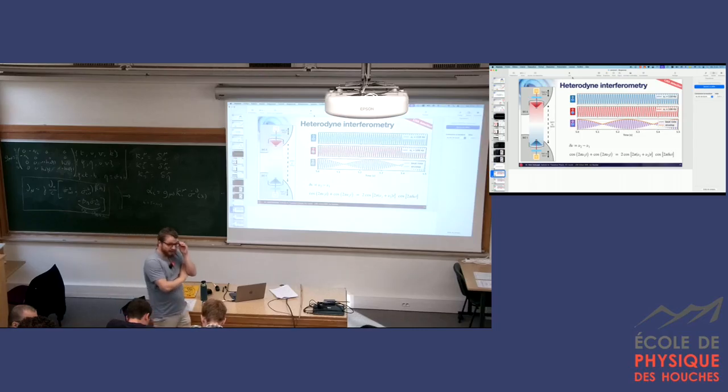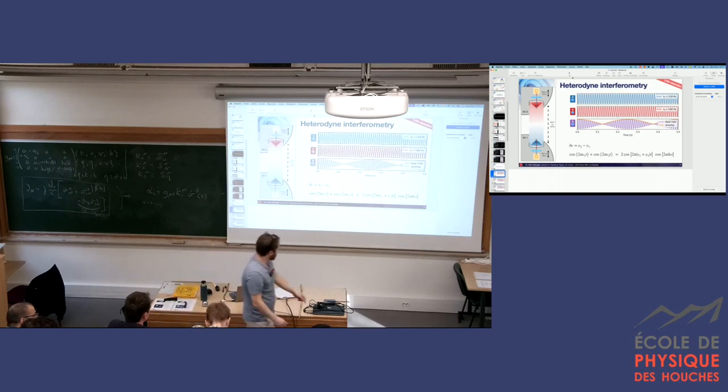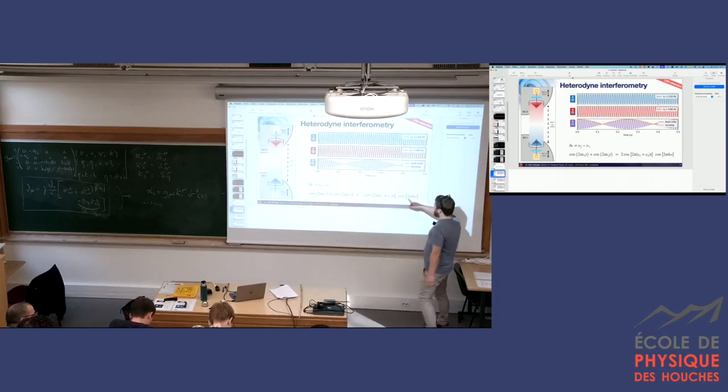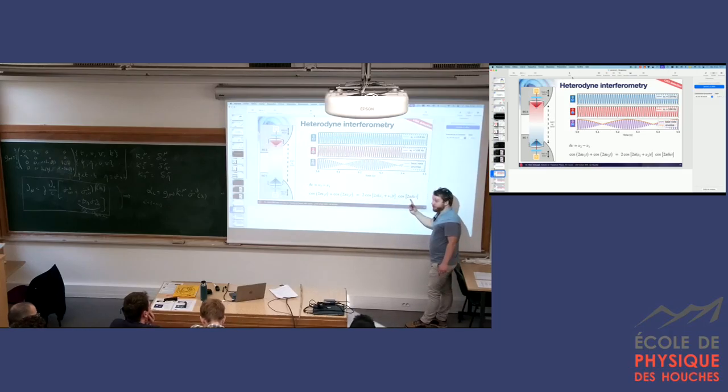Okay, just to make sure I understand the logic of the measurement here, you were showing this single link response, which is this Y quantity. Yeah. So it's a relative difference between frequencies. Is this what is actually being measured? Yes, because the beat note, as you see here, when you combine the two signals, you get two components. You get the sum of frequency, this very fast modulation, and you get this envelope. And the envelope is the difference of frequencies. You can measure the timing of this envelope, the phase modulation, and that's exactly what we measure.